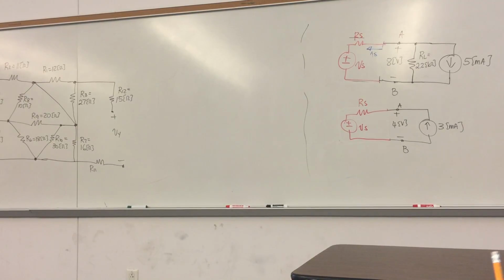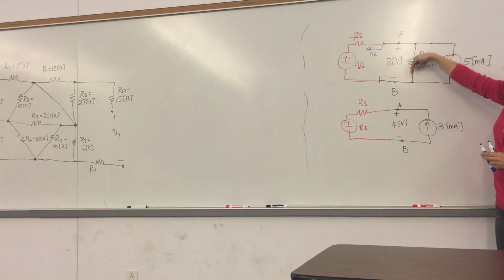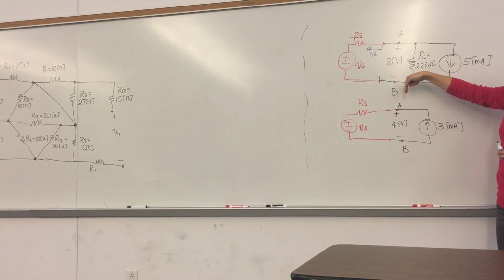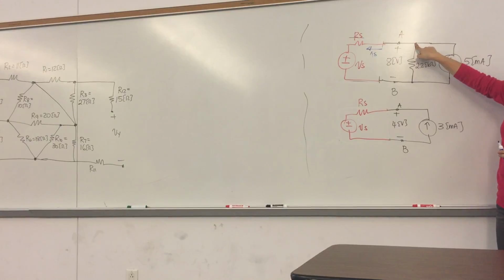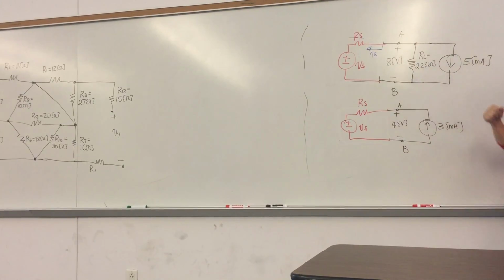Why is it not negative 8 volts minus 2.2? Because 8 volts over 2.2 kilo ohm will be that current flowing down, in passive sign convention. And I'm writing the KCL at that point, leaving the node, that's why plus. This is equation 1.